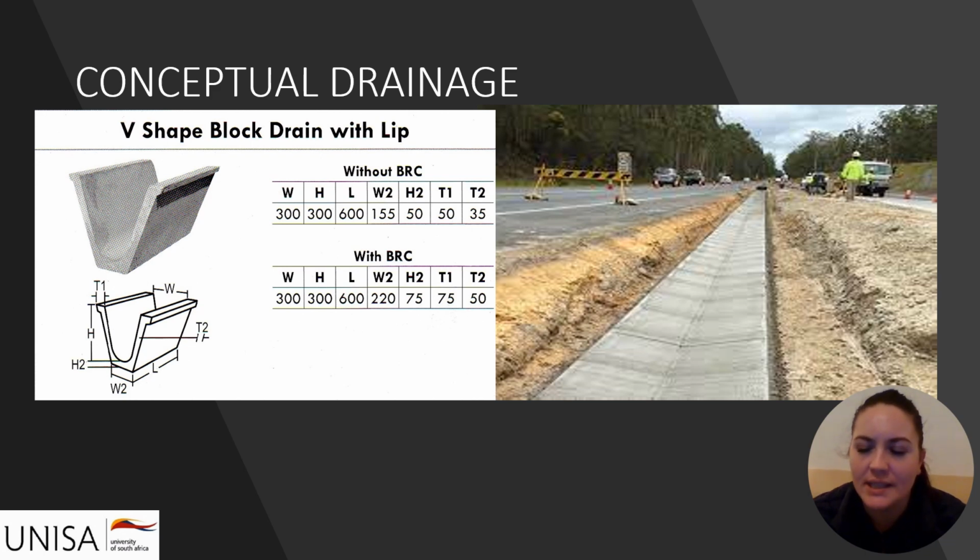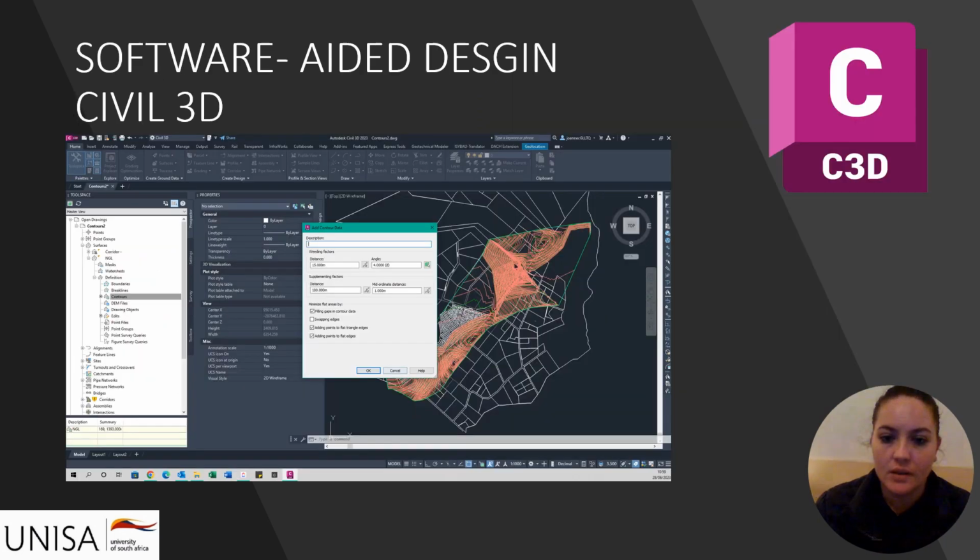Where a low point is encountered at the top of the road, a chute will be built to break the flow of water and slowly discharge into the road reserve, which was set out as 40 meters. It will act as an attenuation dam, allowing the water to flow into the road reserve. If the road is ever to be extended and an increase in lanes is considered, then an underground stormwater system must be built and designed correctly.